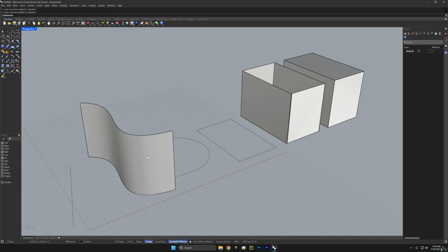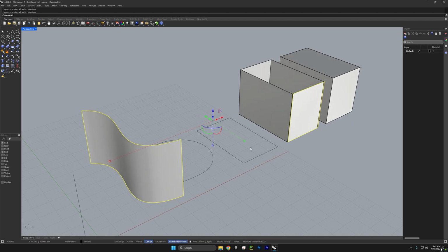Now there is a little problem with turning the points on for this and this surface. It is that these are technically extrusion objects in Rhino. So if we turn the points on, we're going to get kind of a weird result where there's just going to be maybe 2 points in space. We really want to turn these into regular Rhino geometry.